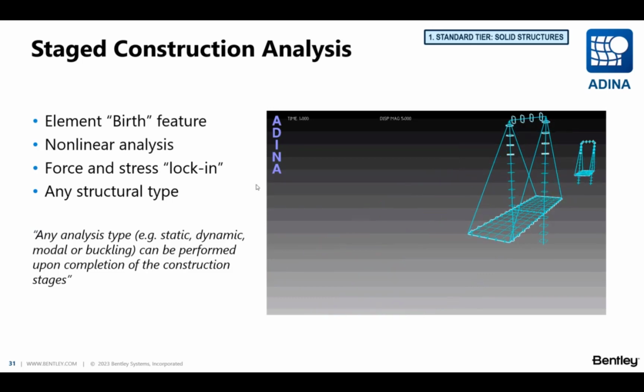We can apply this to any structural type, and any analysis type, whether it's static, dynamic, modal, or buckling, can be performed on completion of the construction stages. So this could be another import from STAAD.Pro, and then we can set up our stage construction analysis in Adina.